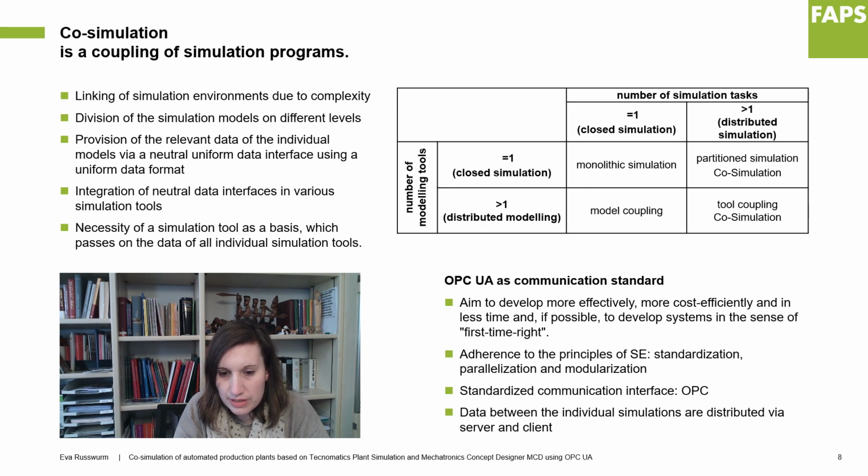Just as the need for standardization and modularization in the software landscape is becoming louder, there is an increased demand for standardized interfaces between several components at the communication level. In this context, OPC UA has emerged. OPC UA stands for Open Platform Communications and is a communication protocol that is used primarily in the context of Industry 4.0 and that enables standardized access to devices, machines, and other systems in industrial environments.